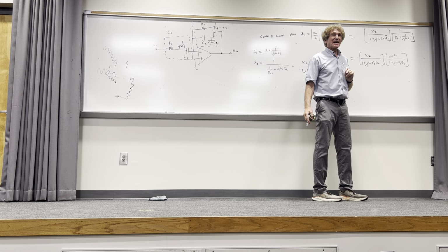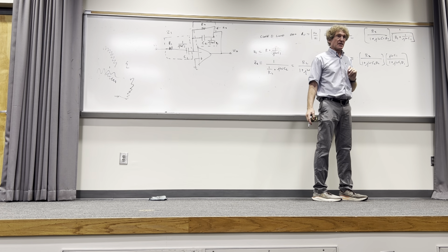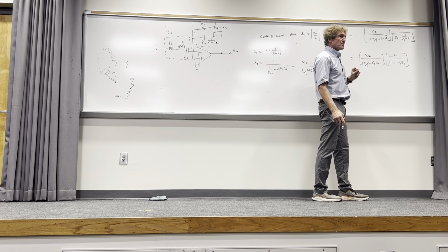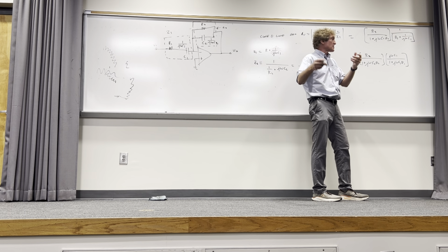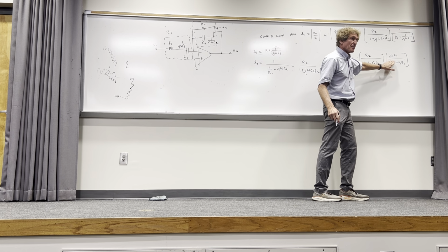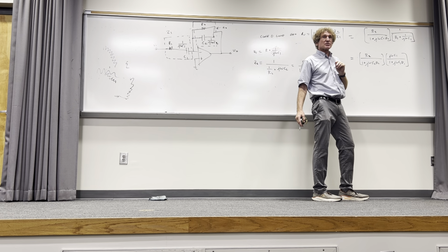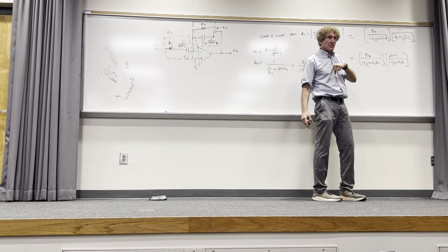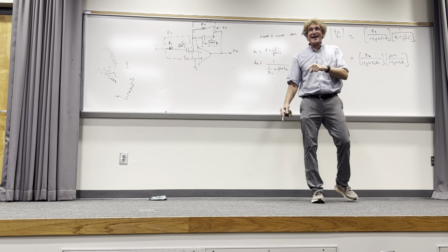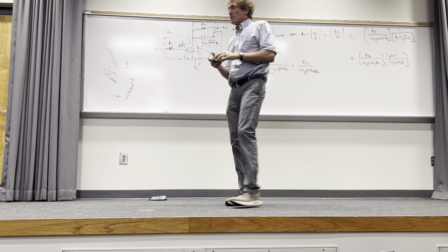Now take the limit as omega goes to infinity. As omega goes to infinity, what do you see happening? Just look. I have an omega squared downstairs when you square it. Isn't that right, class? When omega is going to infinity, the 1's go away. You effectively have an omega squared downstairs. You only have an omega up top. It's going to 0. You with me? So that tells you at the extremes that's going to 0.